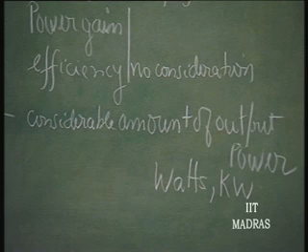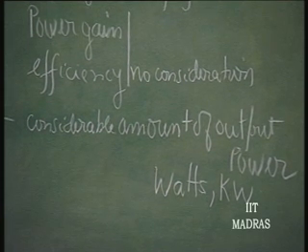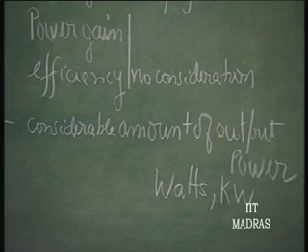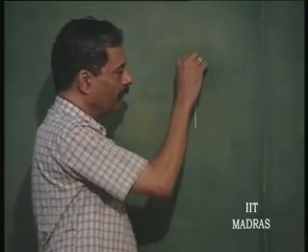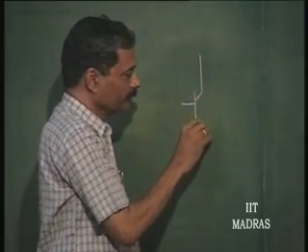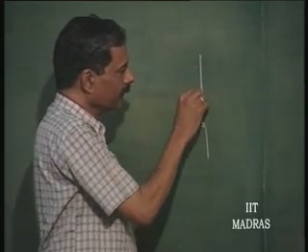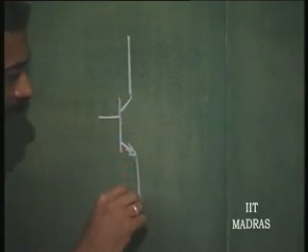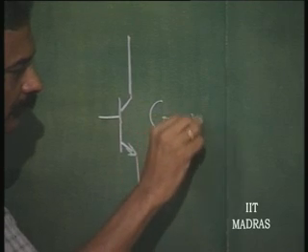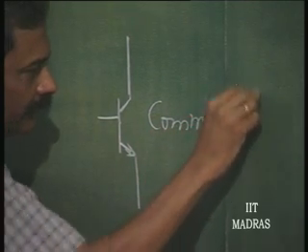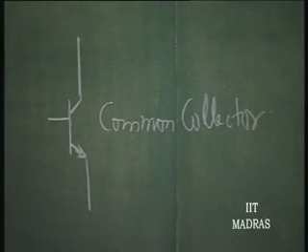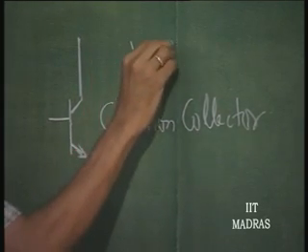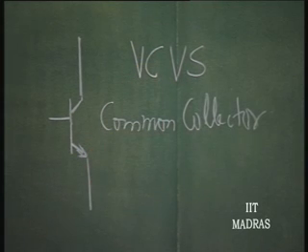So, what are these amplifiers that we have already discussed? Let us consider a power amplifier, its characteristics. Let us consider a common collector stage, because this is basically a good voltage controlled voltage source, can also act as a buffer stage.